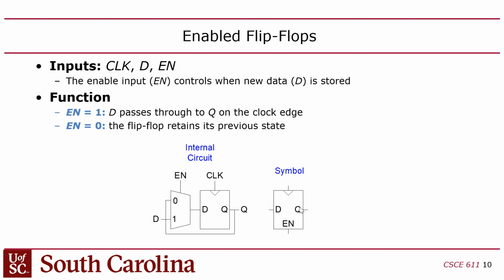Because otherwise, the hex displays would be changing every cycle, and they would be changing to, I think, the contents of the RS register. So if you have IO2 out always enabled, then whatever your register file happens to be spitting out on the first read port is going to be shown on the hex displays, which means it's going to be changing up to 50 million times per second. It's going to be changing so fast, I think it'll probably just look like 8s or something on the hex displays.